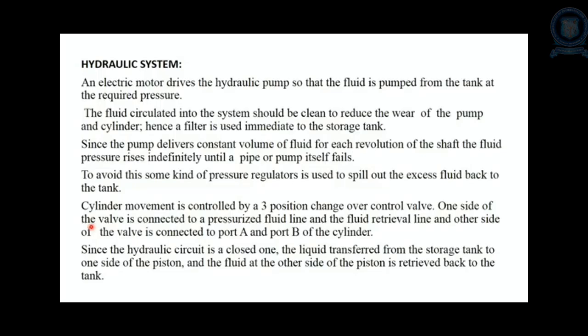So in this, first we are going to study about the components of hydraulic system. In a hydraulic system, an electric motor drives a hydraulic pump so that the fluid is pumped from the tank at the required pressure. The fluid circulated into the system should be cleaned to reduce the wear of the pump and the cylinder. Hence the filter is used immediately after the storage tank.